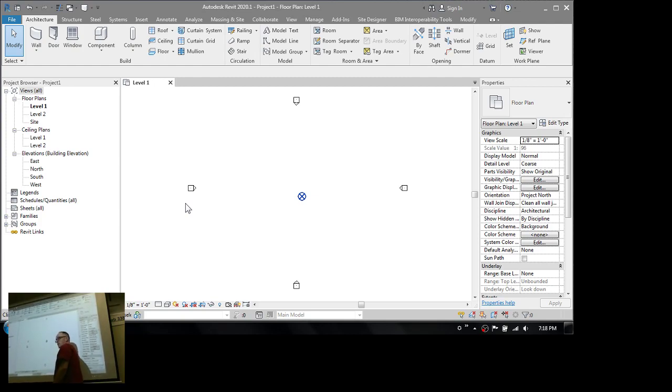And of course that's easy to do unless you're doing an airport or some big, massive transportation project. So this is one of the reasons that Revit is not likely to be used by the road building industry. Question? So if we have something out of this scope, do we get a message? Yes. So the question is, what happens if you do have something that's larger than that? Revit will let you do it, but it'll give you a warning that you could have some display weirdness. So that's why you want to avoid it, if at all possible.